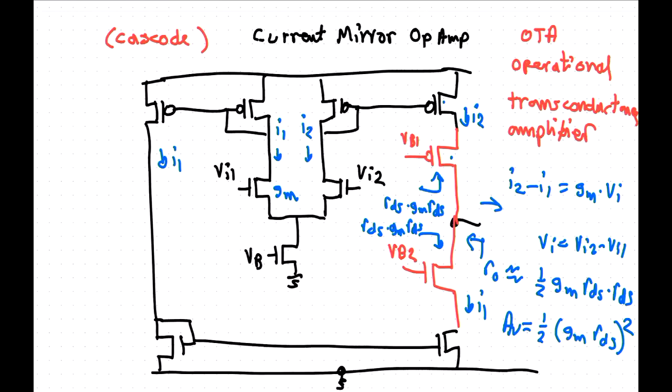You can use capacitors instead. It's a little bit more fiddly, but that's perfectly fine. They don't add noise, and you don't have to drive it. So it's very, very common to use OTAs on chips instead of op-amps. That is your default component, even if it looks a bit funny.